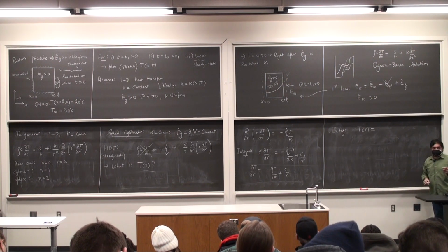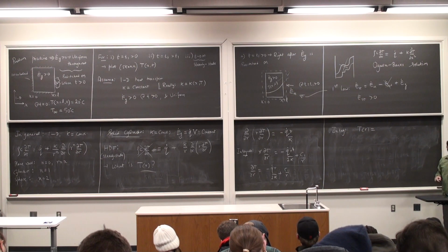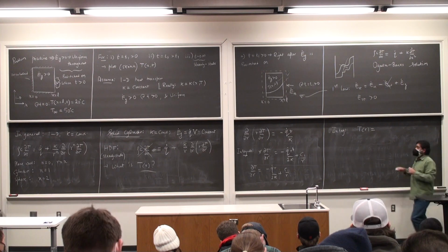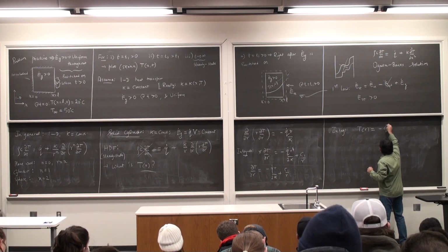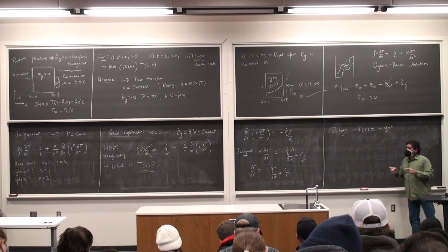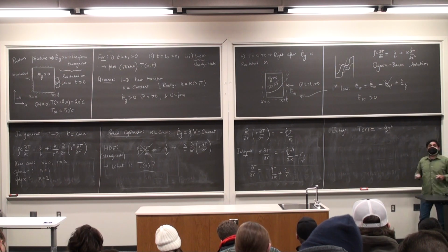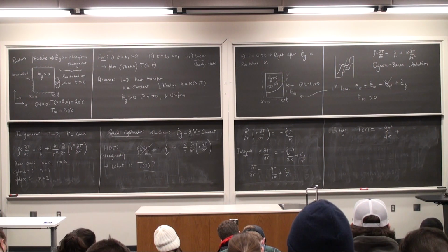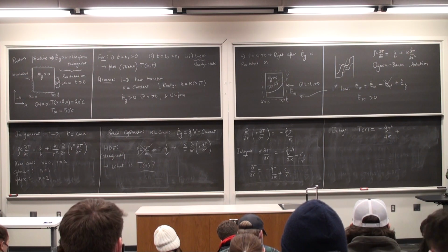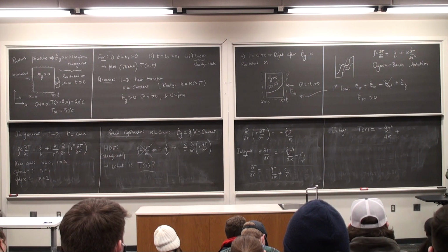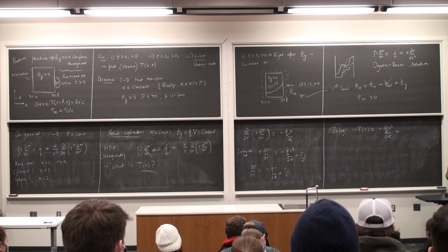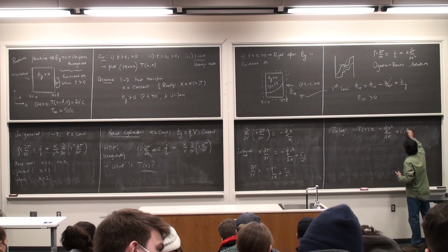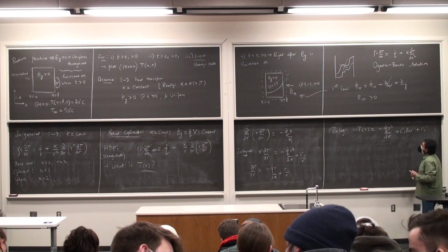T of r: q dot is constant, 2 is a constant, hopefully k is a constant given to you in the problem, and a function of r, so it becomes r square. Instead of 2, because I am integrating r, I get another factor of 2, so this is 4k. What is the integral of 1 by r dr? Natural log of r, there's not much thinking to do. Plus c2.